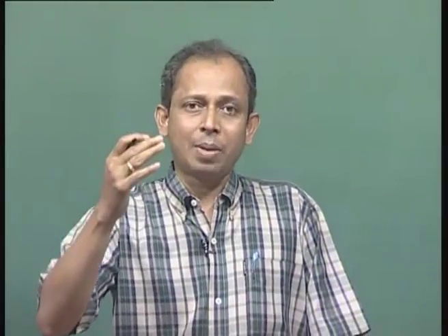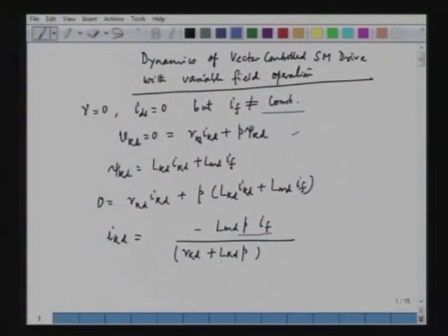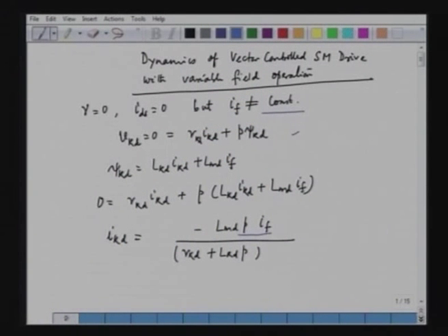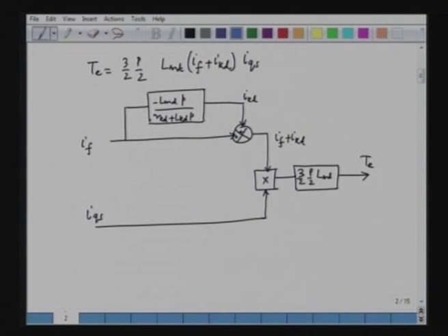We have the damper inductance and the damper resistance. So, the damper current will die down at a time constant, which is equal to the damper inductance by the damper resistance. So, this is the time constant Lkd by Rkd. With this time constant, damper current will gradually die down. In the steady state condition, the flux will reach the final value, and the torque will also adjust to the final value. So, we will see that the torque response is not instantaneous.